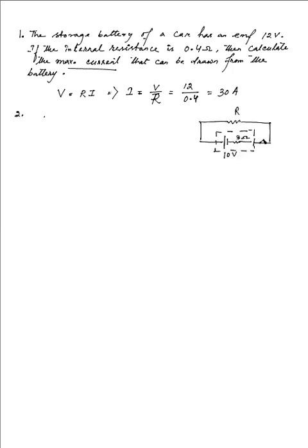Now in the next question, you have a battery. This is the battery arrangement shown by the dotted lines. Enclosed within that dotted line, you have a 10-volt battery with an internal resistance of 3 ohms, connected to a resistor having a resistance, supposedly, R. Now if the current that flows through the circuit is 0.5 amperes, we need to obtain the value of R.